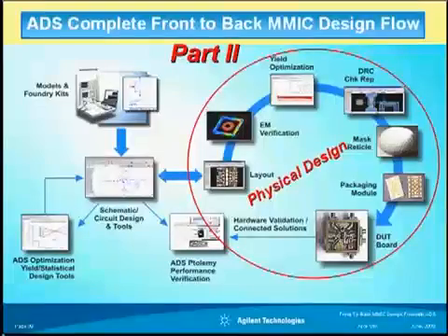Now that we have successfully created a solid design in the schematic page, we are ready to take it to the next level, which is the physical design part. Regularly updated foundry, device, models, and layouts are synchronized in both schematic and layout pages. So with ADS, it is very easy to create physical designs. Either you can do it by auto-generating a layout from the schematic via design synchronization, or by manually placing the layout artwork. Let me explain all this in detail in the next slide.